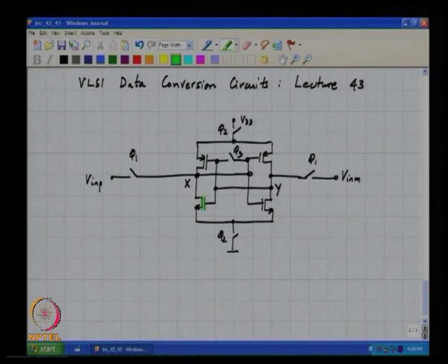because static mismatch in the transistors which form the main regenerative pair, as well as mismatches in the switches and the parasitic capacitances at x and y, equivalently appear as if you are not comparing Vx and Vy, but some Vx minus some delta V1 and Vy minus delta V2. So, it is an error in the threshold of the latch.